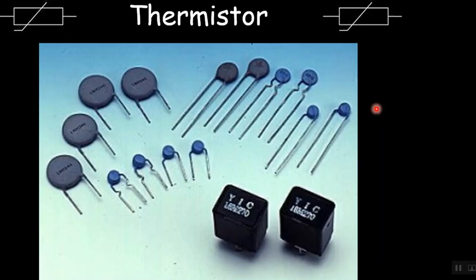Typically your tongue and your skin can feel temperature, so your skin and your tongue have similar functionalities to a thermistor. A thermistor measures the temperature and basically sends the current through. So when it is cold, the thermistor can block the current, and as it increases in temperature, the current starts flowing. So when it's low temperature, there's a high resistance, and when there's a high temperature, there's a low resistance.